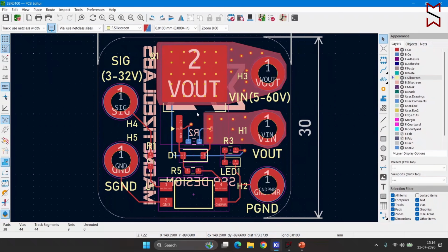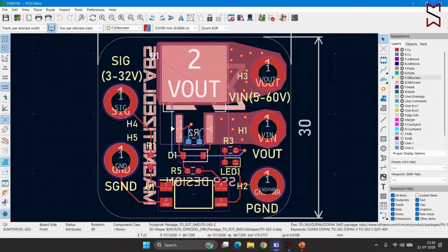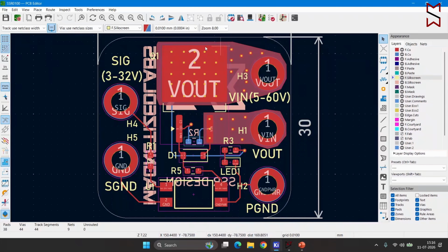In the PCB, the same setup. We have given the mounting hole input for signal and even for the power input and output terminals. This is the high power P-channel MOSFET. We have used a big plane to conduct the whole amount of current. If you want, you can add a little bit bigger plane when you are designing, or you can add a piece of heatsink on top of the P-Channel MOSFET to manage the thermal performance.